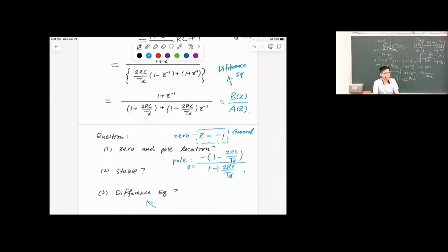And is that desired in our case? We're designing a low pass, right? So we're designing a low pass, and now bilinear transformation seems to guarantee that we get 0 gain at Nyquist. That's a good property. Okay? It turns out that this is quite general. When we design a low pass by bilinear transformation, the zero is guaranteed to be located right there at z equals to -1. This is a general property. Let me put an exclamation mark because we are happy at this moment. Okay, this is a good design, if what you want is low pass.